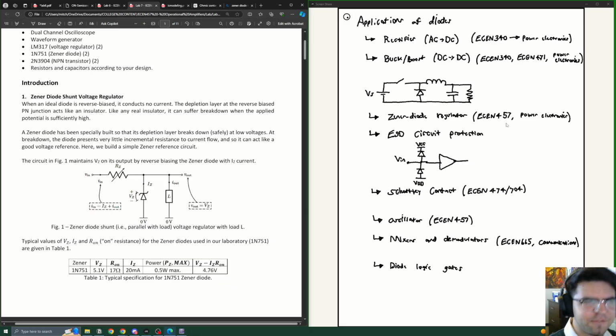There are much more sophisticated ESD circuits than ones like this, right? But this is an example of, let's say you apply some input voltage. The input voltage is always going to be within your two power supply rails, so attaching a circuit like this does nothing during normal operation. But let's say we touched the IC package, and now VIN is going to be a gazillion volts, thanks to the brief moment of electrostatic discharge coming from our body. Well, now if the input voltage is really, really high above the power supply voltage, the diode just shorts it out and takes all that extra current to the VCC, preventing us from breaking the actual device that we care about.